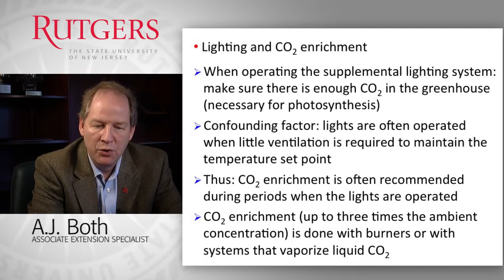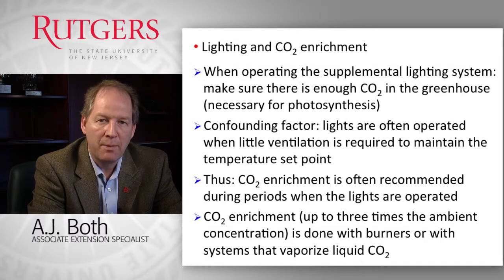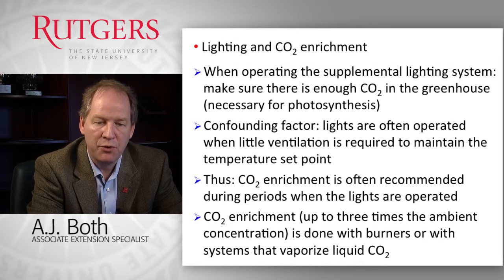So when we do CO2 enrichment, we go up to maybe as high as 3 times the ambient concentration, which currently is around 400 parts per million or micromoles per mole. Because if you go higher than that, it's typically not cost effective. So up to 3, sometimes 2 to 3 times the ambient concentration is sort of the maximum rate of CO2 enrichment we want to try to shoot for.